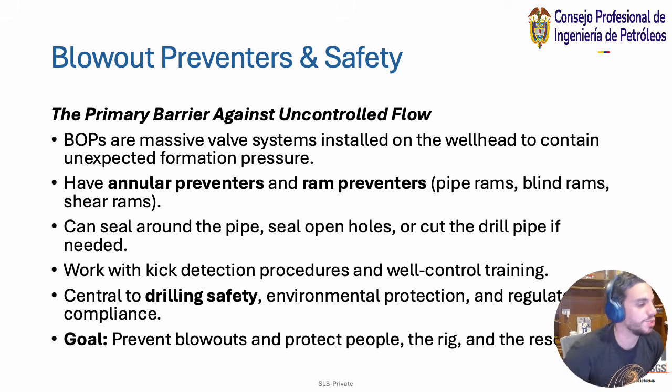And that brings me to a topic: the surface of a rig has its own tools, like the Christmas tree, the valves, and the pressure head, and all these things require their own expertise. There are different companies that work on it, so that's also a separate field you can get into. But the blowout preventers are these big valve systems, and they have annular preventers and ram preventers, and they can seal around the pipe, and they can seal open holes or cut the drill pipe if needed.